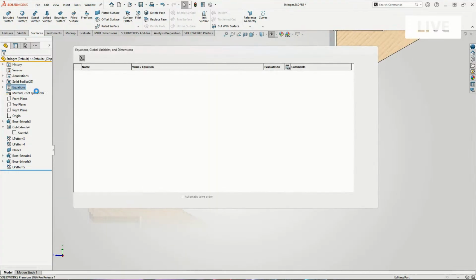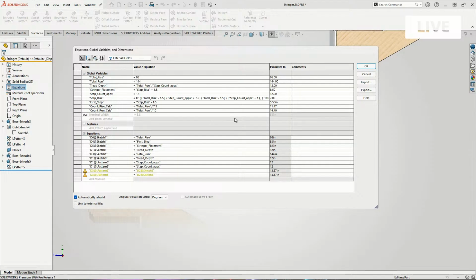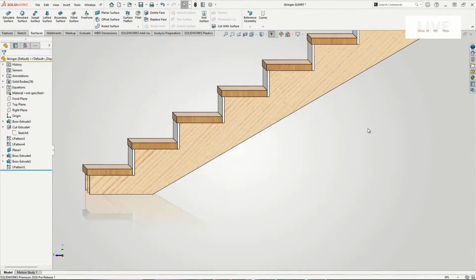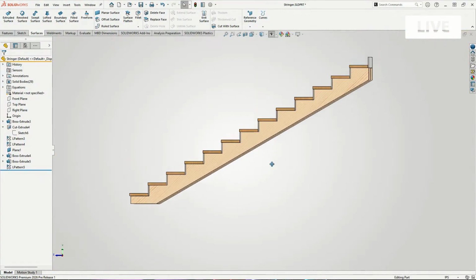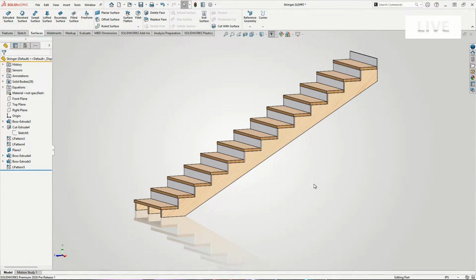That's when I realized after playing with it that my step count, which is 12, and this is saying 11 to 14. Well, if we add in, let's just average that and do a 13. Add a new stair to it. Click the OK, and that looks good. Yeah, so I've got a really smart model.